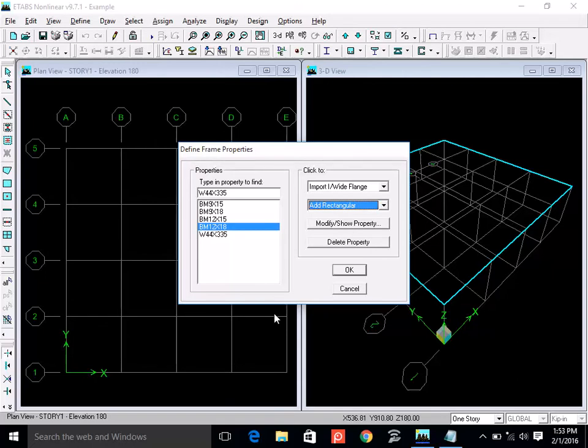It was the time when we had an earthquake in 2005. So we submitted the first design on zone 3, and then earthquake came. And then we had to revise our design completely on zone 4. Although Rawalpindi is not in zone 4, but still they wanted that it's a hospital, it's an essential facility, so we want some higher zone consideration. So that's why the sizes were too big. More of a wall than a column. But except that, I never have experienced that somebody used 9-inch thick column.